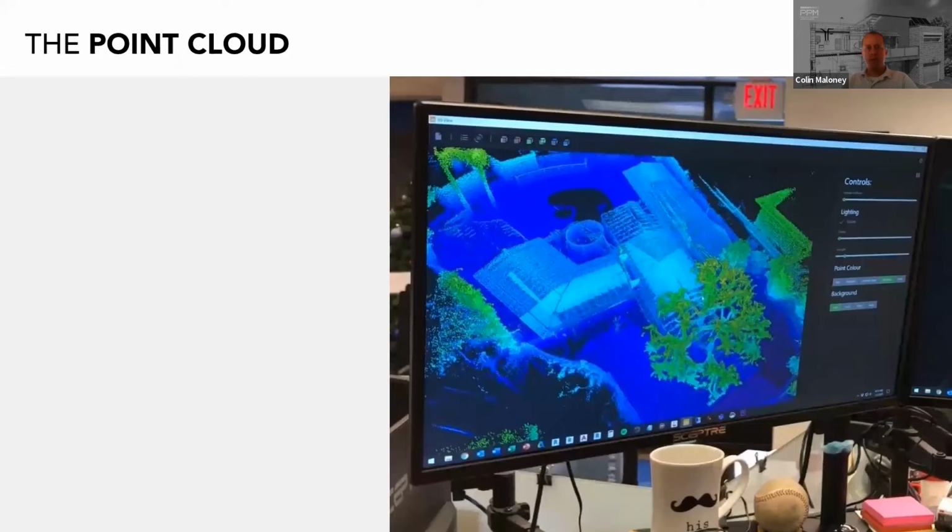Reviewing your data well before attempting to create a set of as-built from a point cloud is a must. If there are any kinds of errors with your cloud, which do happen, then using the bad data can either stop you in your tracks later when you're drafting or modeling, or even worse, result in an incorrect set of as-built and change orders and all sorts of problems later on.